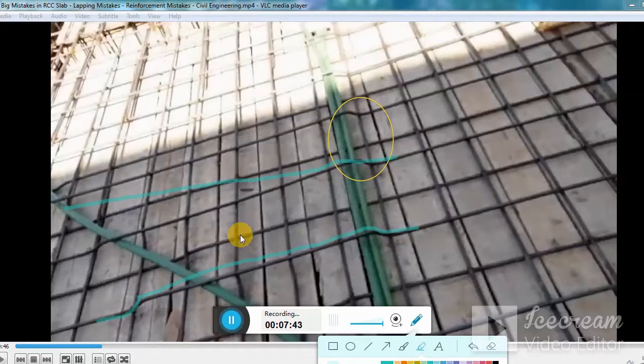Now it's not passing over the support, right? There is no support. So why are you bending the bar? They just bend the bar due to these pipes. And you see there are two pipes which are running basically at the same location. And what I told you in the initial part of this picture is that we don't allow such pipe arrangement. If they are using them, they must separate them. We object to such kind of practice.